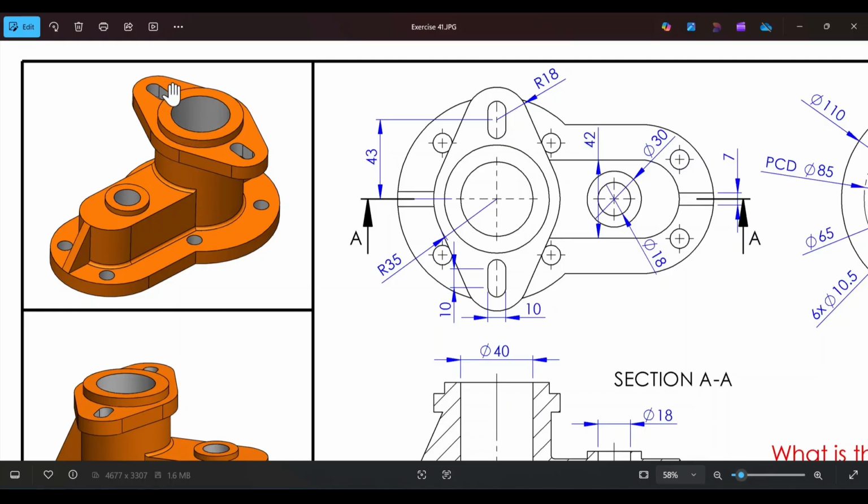After that, we're going to move on to step 3, which involves creating this top flange. Of course, there's going to be plenty of sketching in the process, followed by an implementation of the extruded boss base tool. After that, we're going to work on creating this central protrusion here. We're going to sketch out the 2D profile, then use the extruded boss base tool.